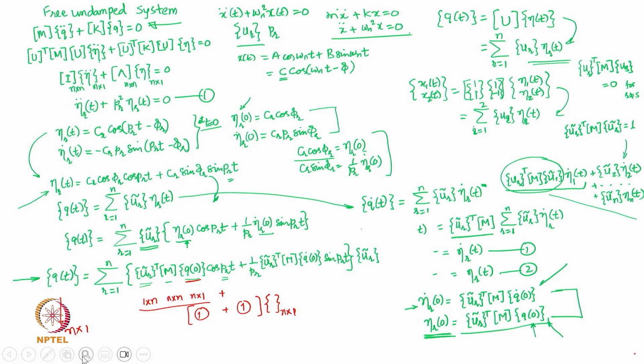You don't worry about the size of all these matrices, because you can simply write a small code in any platform that you feel like. What all you will need is your eigenvector matrix, your U, and the spectral matrix, which of course you have to get from your eigenvalue analysis. Once the eigenvalue analysis is done, the free or forced vibration response will follow through this route. What and how have we been able to find this out?